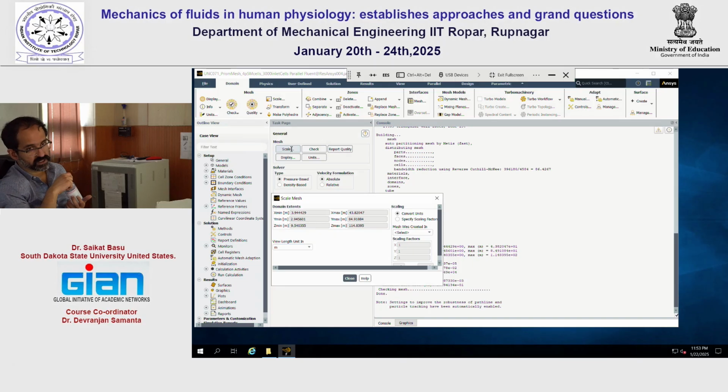Because of the dimension. When I said that the CAD software, the ICEM, is dimensionless, it just does not tell you whether it is in millimeter format or meter format. We know from experience that the length is equivalent to a millimeter. But when you export and then import that mesh in your computing platform, you don't know about the length scale. So Chandan did not change anything on that. And as a result, what he was modeling was what you have over here.